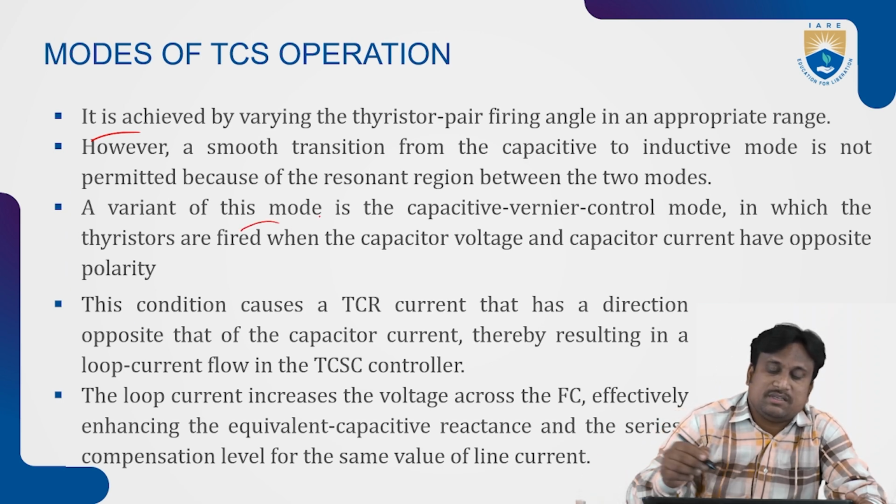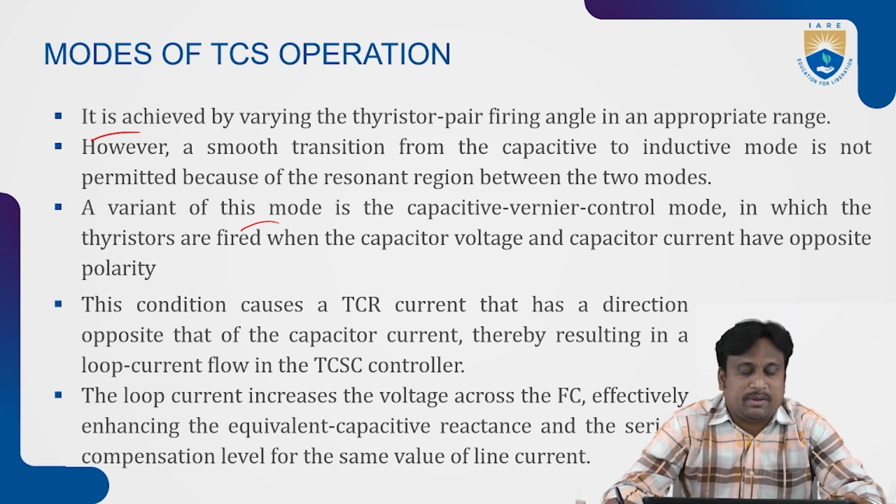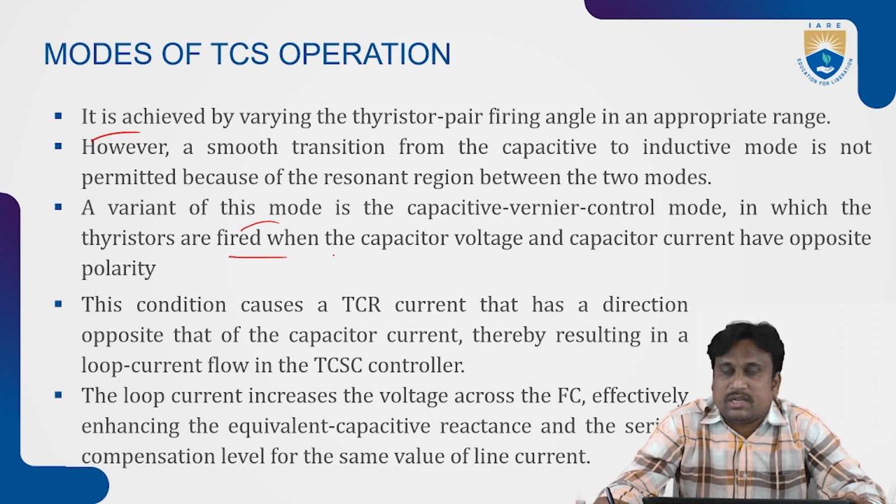A variant of this mode is the capacitive Vernier control mode. Here thyristors are fired when the capacitor voltage and capacitor current have opposite polarity.